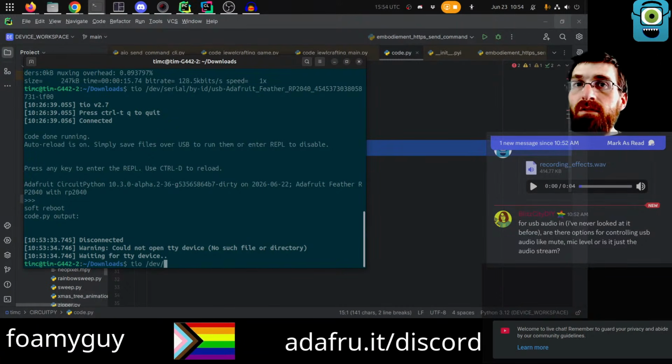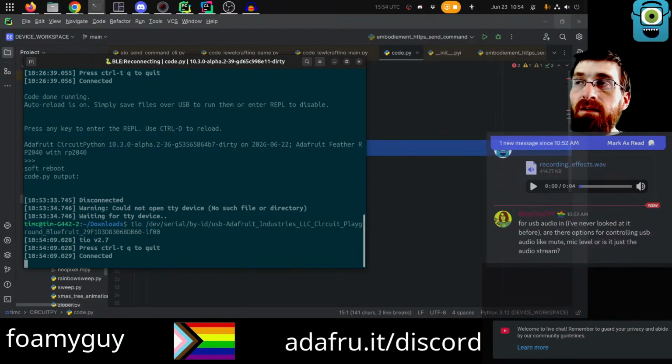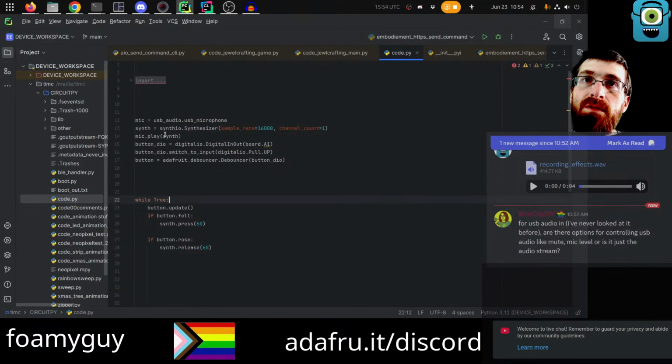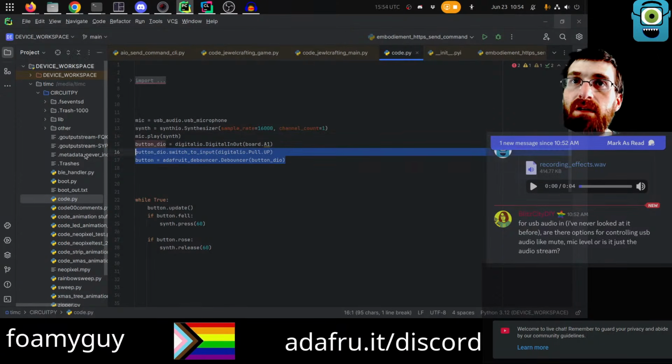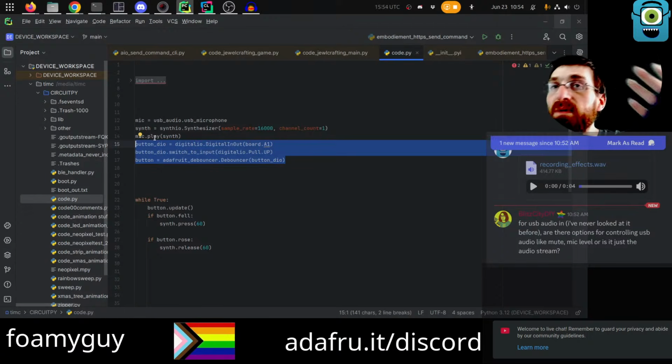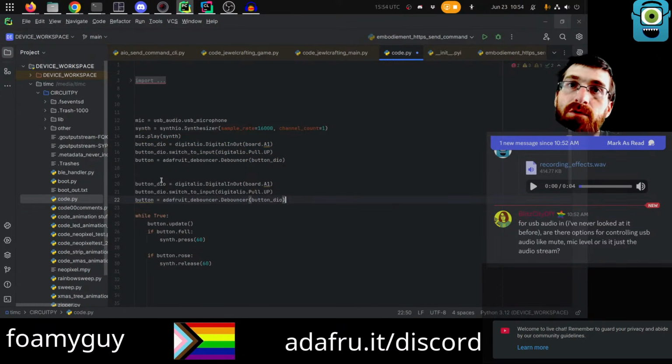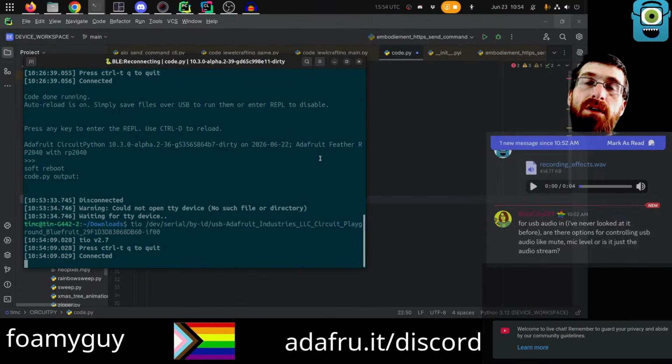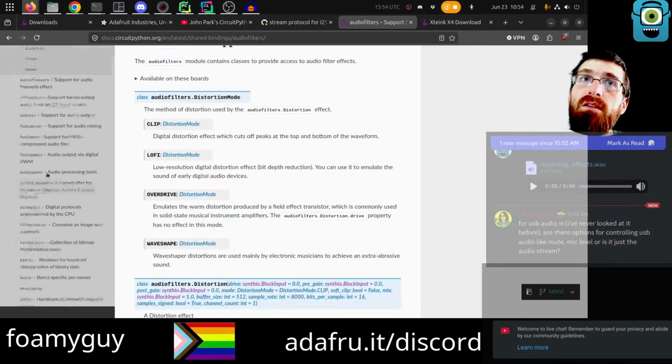The short answer, though, while I'm doing this, I will say you can mute, essentially. There's an API you can use to just stop, like pause, essentially. I'm not even sure what it's called, so we'll discover together. But there is an API that's like the opposite of play. It will turn play off, which will mute, essentially. It'll make it so that CircuitPython is no longer sending audio to the computer. Volume is not built into the API, but what you can do for volume is you can take your source, you can feed your source into an audio mixer.